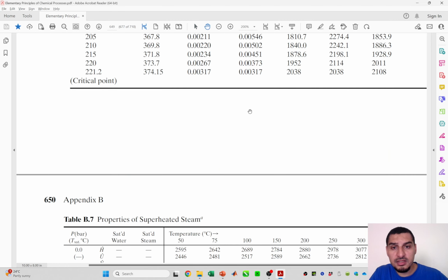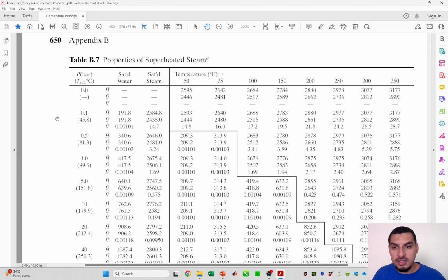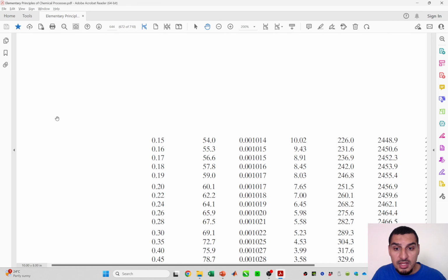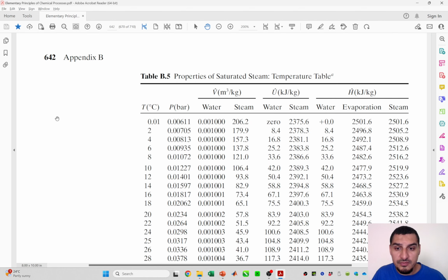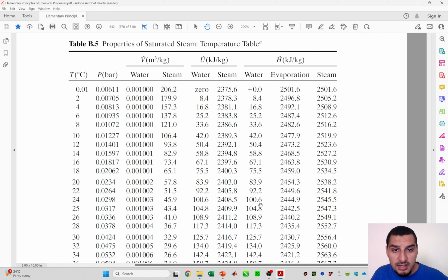we will go back to the pressure table, I mean the temperature table. I'm sorry, and say that here I have 25 degrees Celsius, and I'll take the saturated liquid at 25 degrees Celsius as the enthalpy of saturated liquid as the same enthalpy. Why I'm saying this? Because I know that the temperature has more effect on the enthalpy than the pressure.